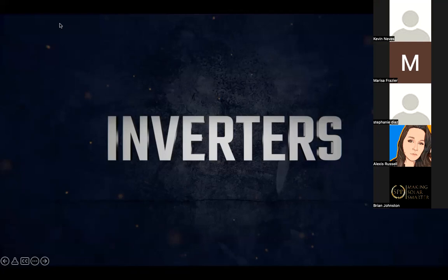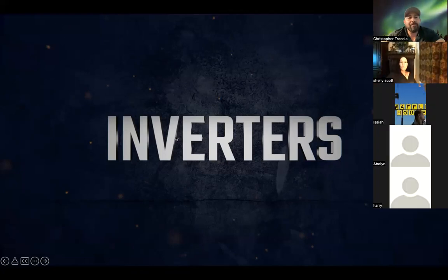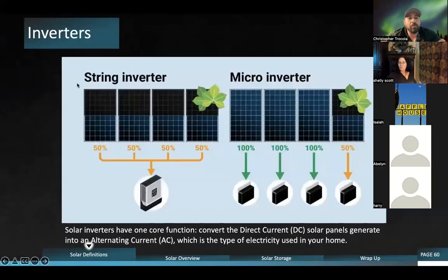All right, let's do this. Inverters are actually one of my favorite things to talk about because it helps tie in a lot of this other stuff. I got a couple of different videos for you guys. We have access to pretty much any type of inverter except for the worst one, which is the first one we're gonna talk about: string inverters and microinverters. Solar inverters have one core function: convert the direct current solar panels generate into alternating current, which is the type of electricity used inside of your home.